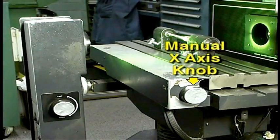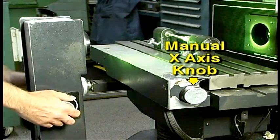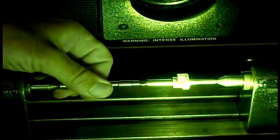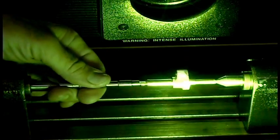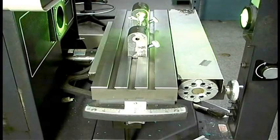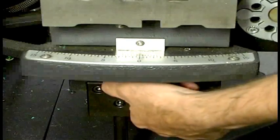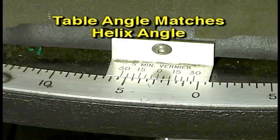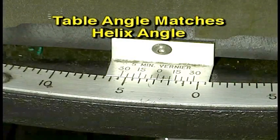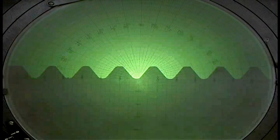This comparator has motorized axis feet adjustments as well as manual adjustment knobs. The workpiece can also be rotated between the centers on the stage when viewing a feature such as threads. The table, to which the stage is mounted, can be rotated around the y-axis. The table is rotated when measuring threads so that the angle of the table matches the helix angle of the thread. This allows the profile of the full thread form to be viewed on the screen.